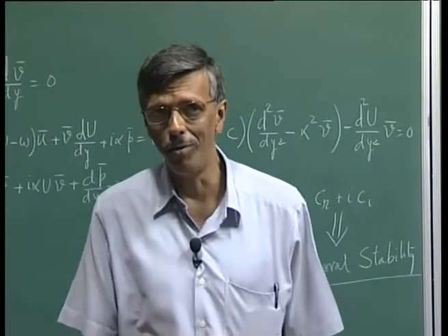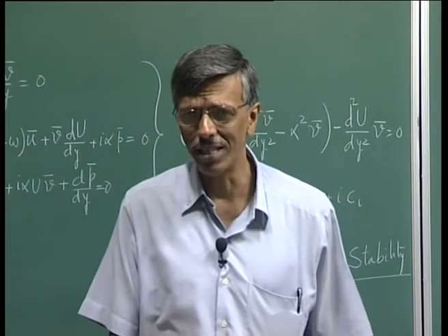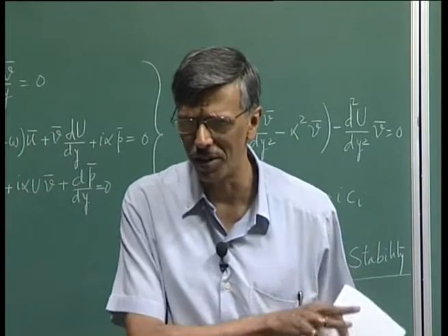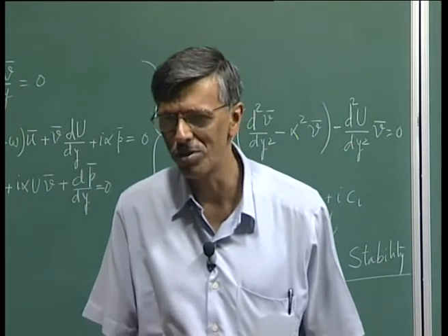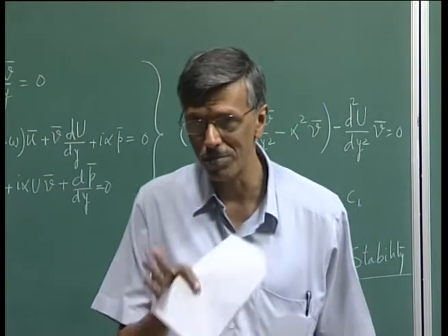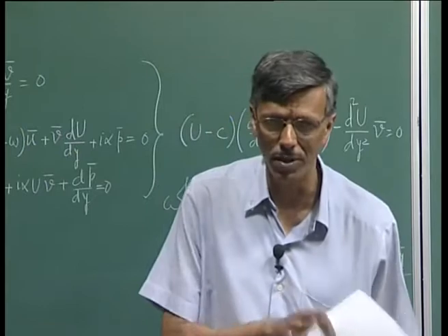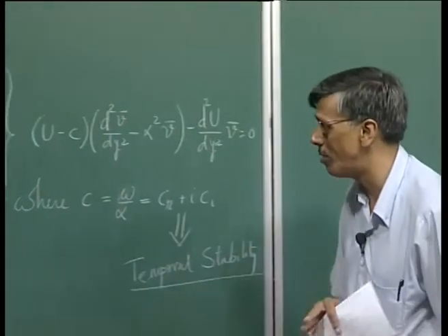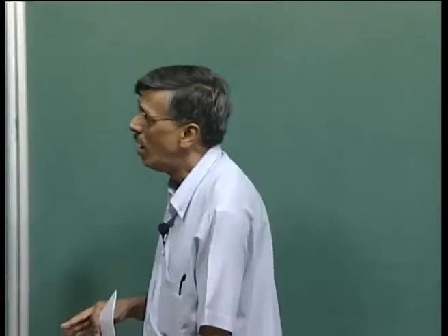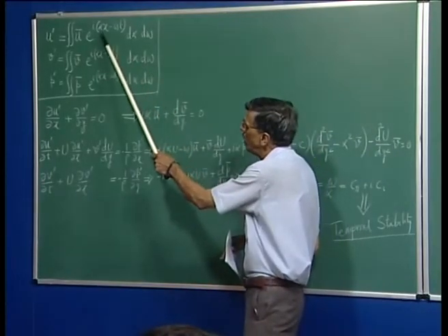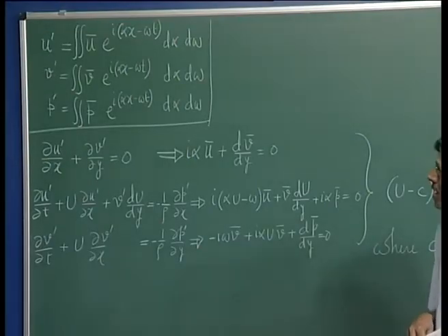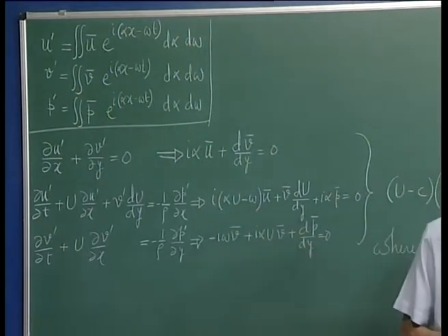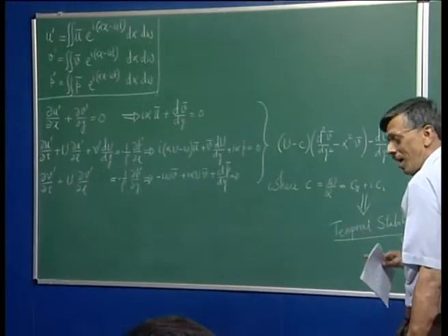For the time being, I will go with the results that are given in most of the books, except the one that we have written recently. We would only talk about downstream propagating disturbance. When it comes to upstream propagation, we will specifically mention it, and I will make you aware of that. Okay. So, alpha r is the phase, alpha i determines the stability or instability. For a downstream propagating disturbance, alpha i being negative would be the unstable scenario. Okay. That is about alpha.